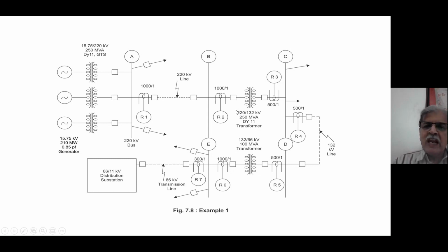Because otherwise, if we add an instantaneous overcurrent unit to all relays, then the TMS will be different, because the relays operate faster if we go for an instantaneous unit for all the relays. So right now we don't complicate everything. We just want to initiate the discussion on setting of overcurrent relays.